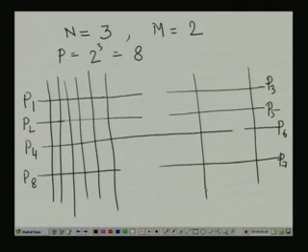So, in this case, instead of 8 by 8, the size is only 4 columns, so 4 by 8. Earlier it was 8 by 4 if it is row wise partition, that means columns are shared. Here it is column wise partition, that means product terms or the rows are shared. So, in this way the PLA can be minimized.